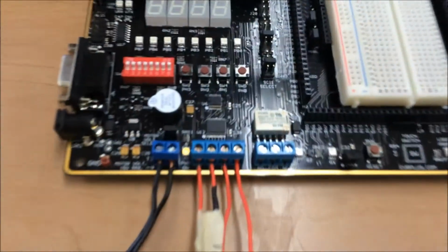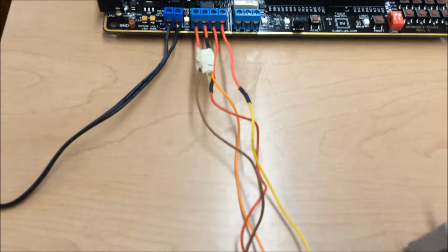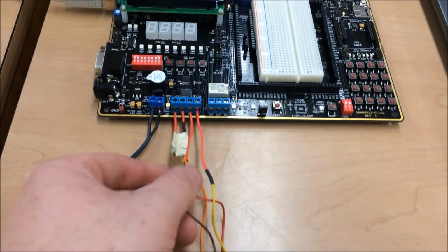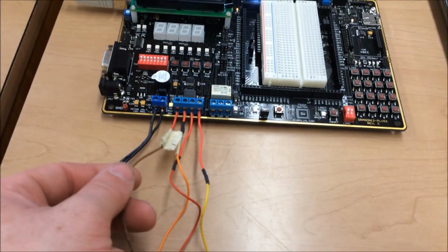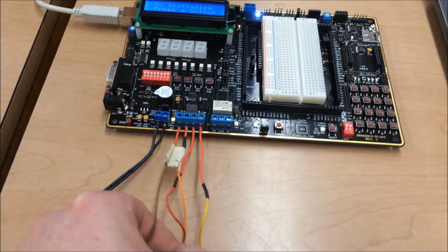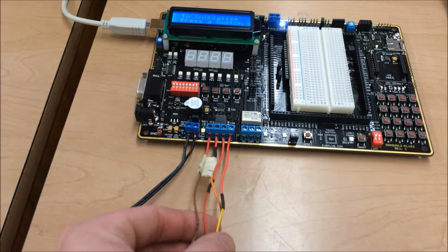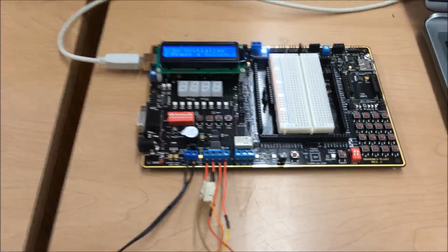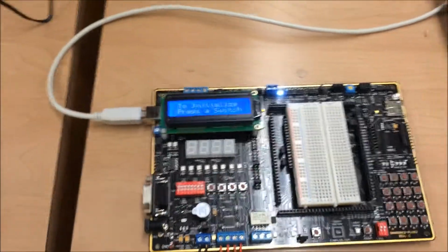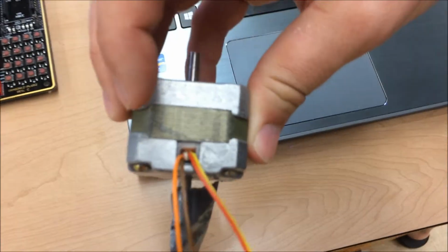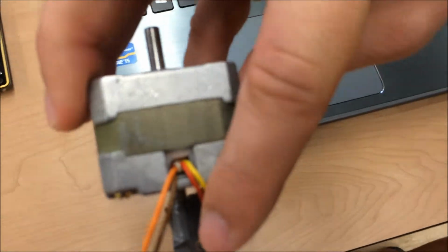So as you can see, we have the 5-volt power supply wired into the board, and the stepper motor wired in. For this particular stepper motor, it's a 4-lead that you might find in the lab, and we have the brown lead going into M1, the orange going into M2, the red into M3, and the yellow into M4. It might take some playing with to ensure that those are properly connected. You can see how they go into the back of the motor and split to their separate ways.